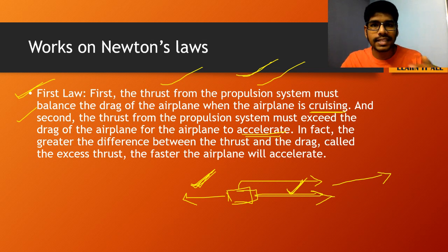If you want to accelerate, if you want to make it move faster, you have to apply a thrust, a force which must exceed the drag force. If the drag force and the thrust you are giving are equal, it will cruise, right? If you are giving a force more than the drag force, it will accelerate. In fact, the greater the difference between the thrust and the drag, called the excess thrust, the faster the airplane will accelerate.